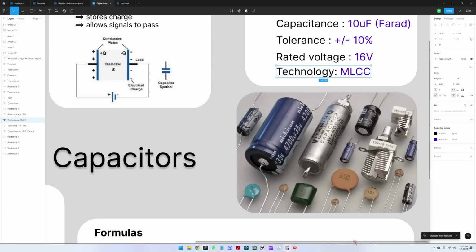What I would like to make quite clear, so it is very important for the electrolytic capacitors, is that you know where the minus is. So the minus is this, you can see an arrow here. This is the minus arrow indicating that this pin here is the minus connection, and this would be the plus connection.